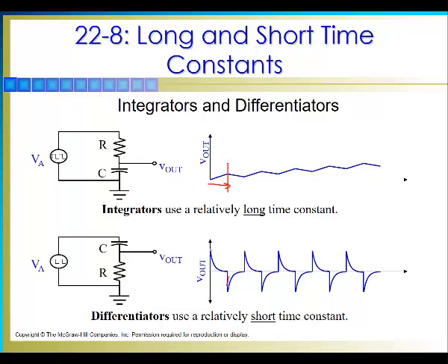It will be the full load at first, then as the source turns on, it starts charging the capacitor, then the voltage on the resistor starts going down. It will go all the way down to 0 before the next pulse on the voltage source goes to 0.